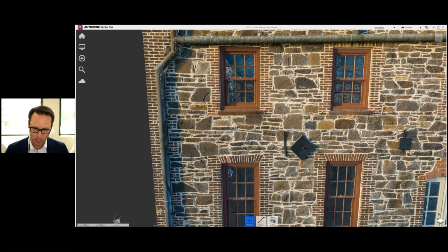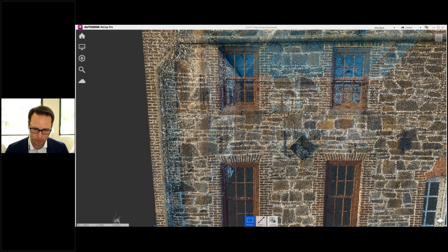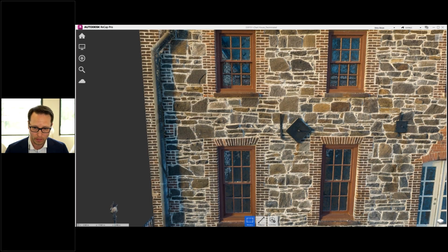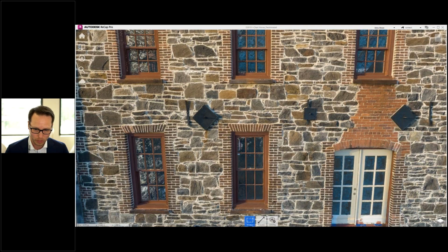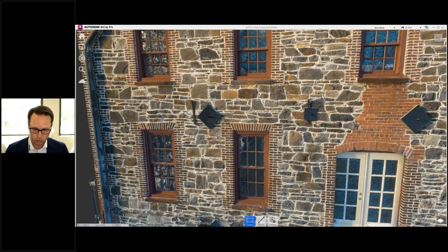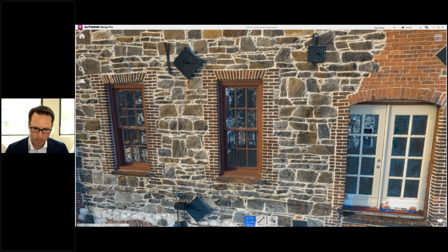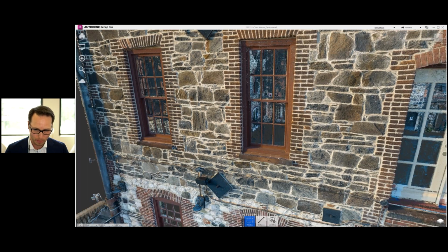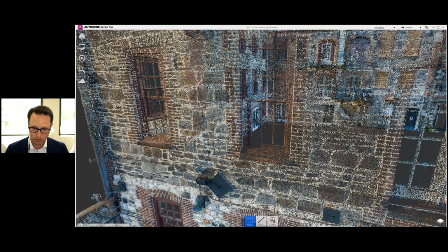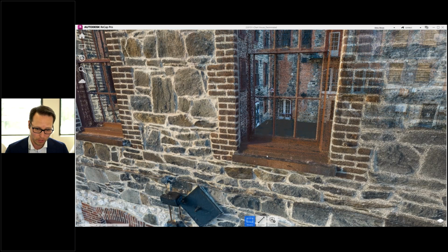We used to take a lot of site photos in order to create models, and by utilizing this point cloud, we avoid switching between the model and photos. Just using Recap and Revit is sufficient to figure out some of these building details.